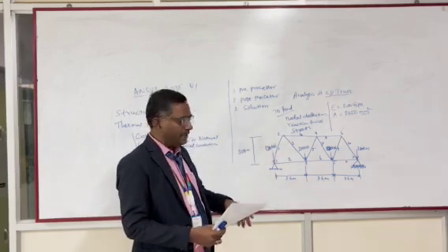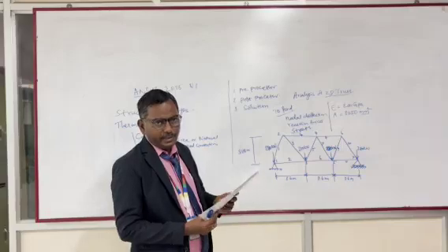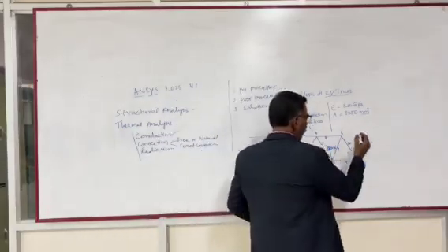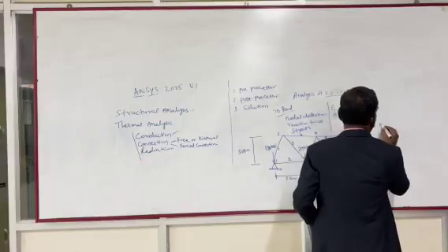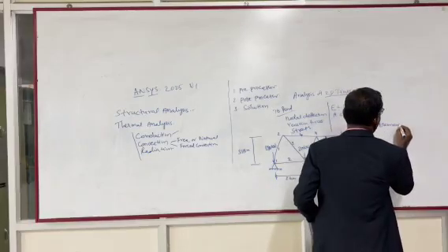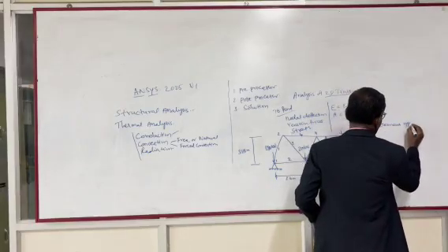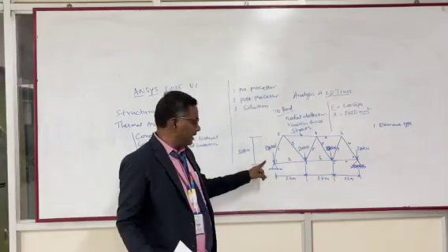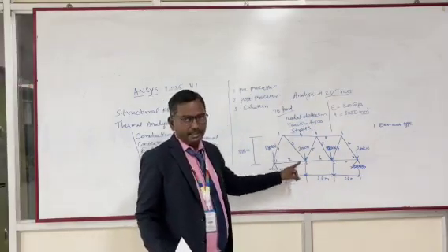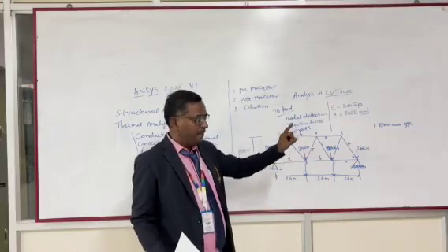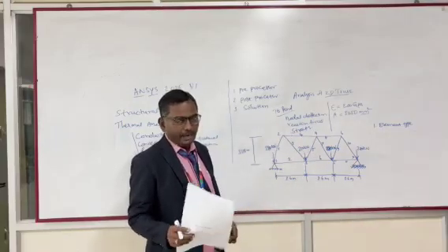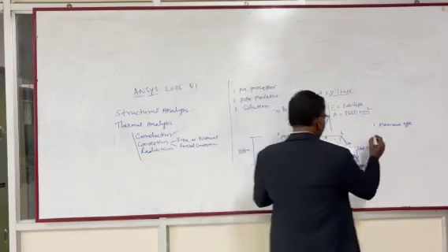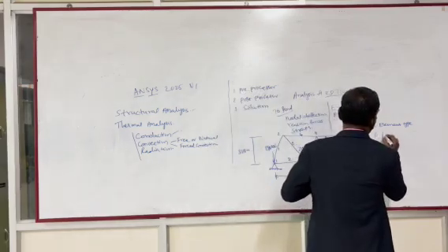Then you can go for the Ansys software. Open the software, and I told you already about the element type. First, you have to fix the element type, the type of element used in the problem. The type of element here is given as truss element. After selecting the truss element, we can go for the real constant or material property. Real constant.